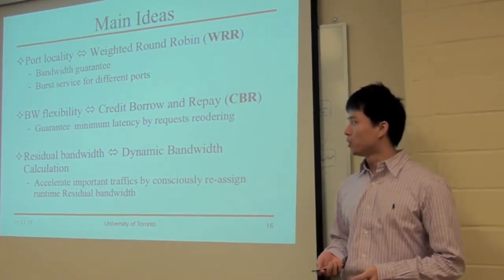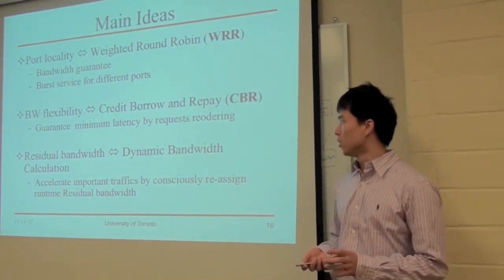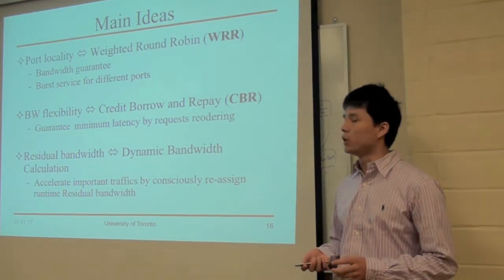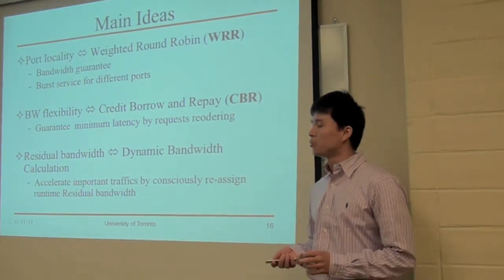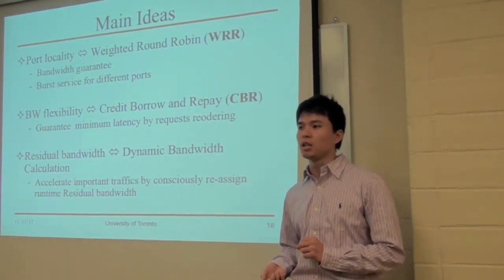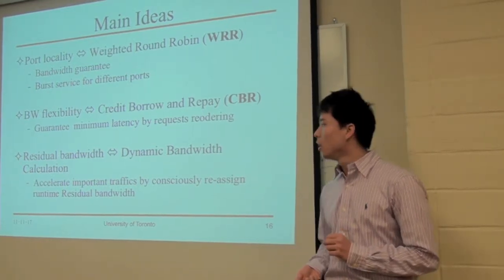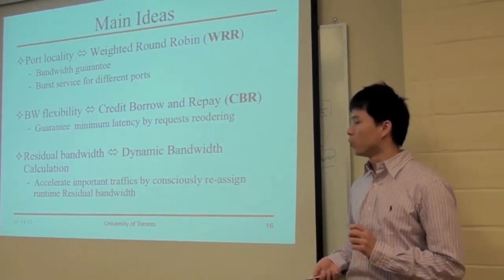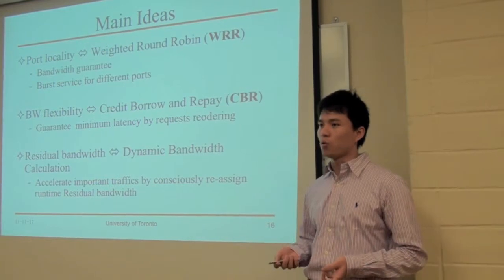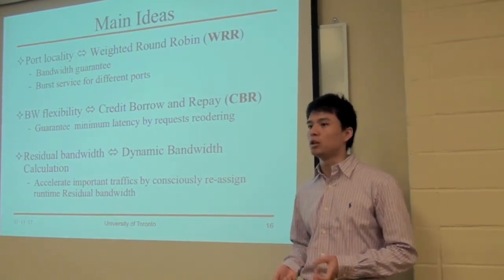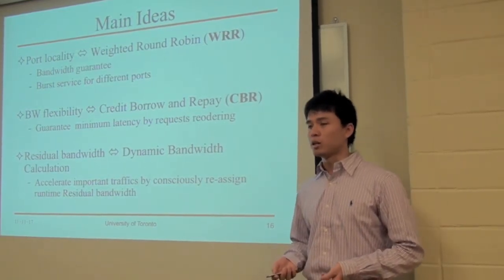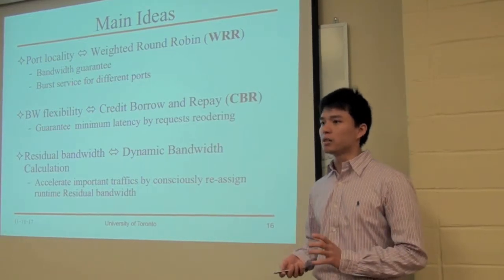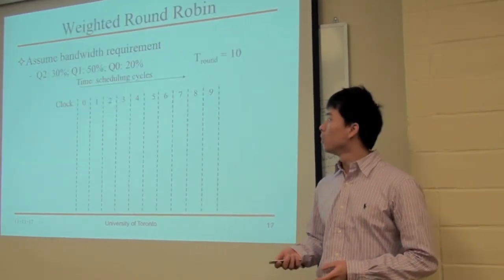For the bandwidth flexibility, we employ the credit, borrow, and repay mechanism to achieve minimum latency guarantee by request reordering. And for the Restive bandwidth, we devise a dynamic bandwidth calculation scheme to capture the Restive bandwidth at runtime and use it to accelerate important traffic.